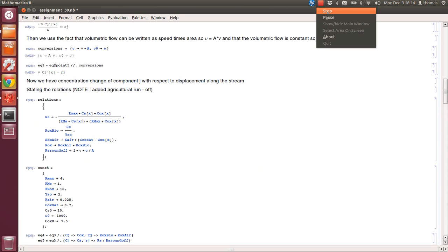And then I have some other lists here again for the volumetric flow and the speed, and they will not be filled with interpolating functions. They will simply be filled with values, because during the reach I will not have any change in the volumetric flow. It is only in the mixing and splitting states that my volumetric flow will change, and that's also the case for the speed.